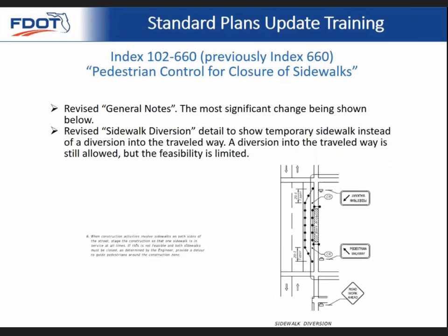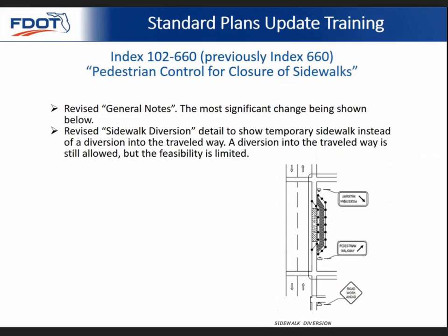Now the sidewalk diversion has been revised. This previously showed a diversion into the travelway, but this isn't typically feasible, and a more realistic option is that a temporary sidewalk or walkway would be placed within the TCP.